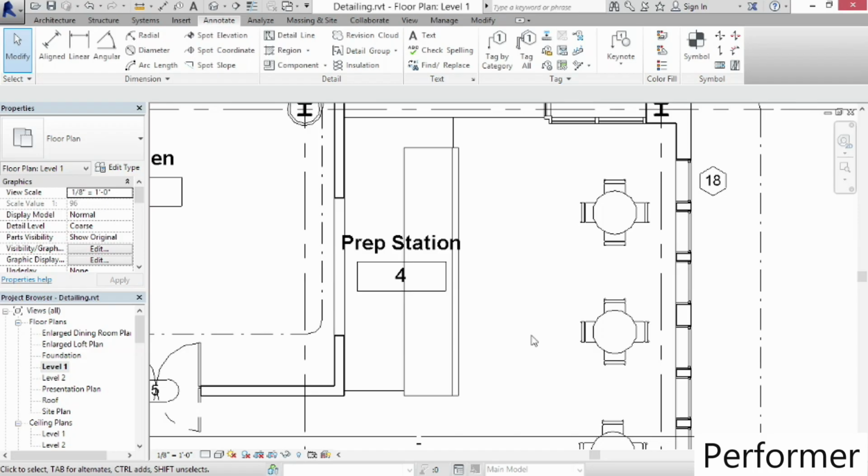And so there are certainly plenty of instances where we have items that are considered construction details that really only show in one place. And the quantity of information that's displayed in those views is at a level of detail that makes it impractical to consider modeling all those elements. Consider things like bolts and screws and flashing and mortar joints and clips and hangers. None of these items really would give you much benefit to adding them three-dimensionally in your model. They would just simply serve to weigh down the model and impede performance without really adding a whole lot of benefit. So at some point, you need to stop modeling and begin drafting.